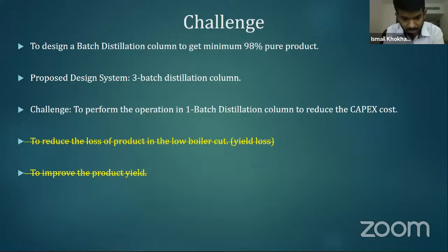So 3% directly came down to 0.035. Moreover, another advantage with this entrainer was that the reflux ratio, which was 35, dropped down to 1. So it was quite a comprehensive achievement by using this entrainer. Selecting an entrainer is also a bit of a task, because you need to know the interaction with the impurities, and you need to evaluate its impact on the product as well.